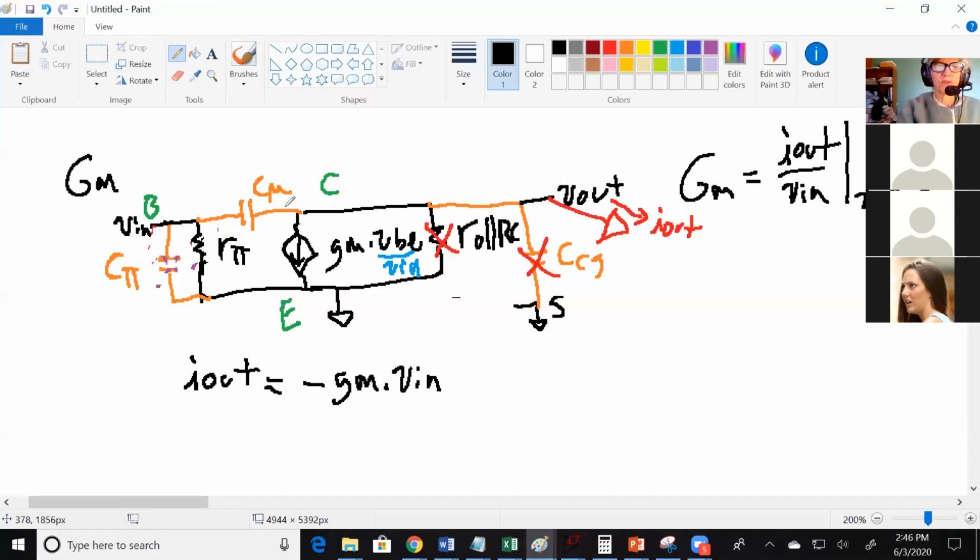So the current going through here, treating this as an impedance, that's supposed to be a Z. Treating this as an impedance, the current going across here is Vn minus the voltage on the other side of the impedance. So Vn minus 0 over the impedance of this.